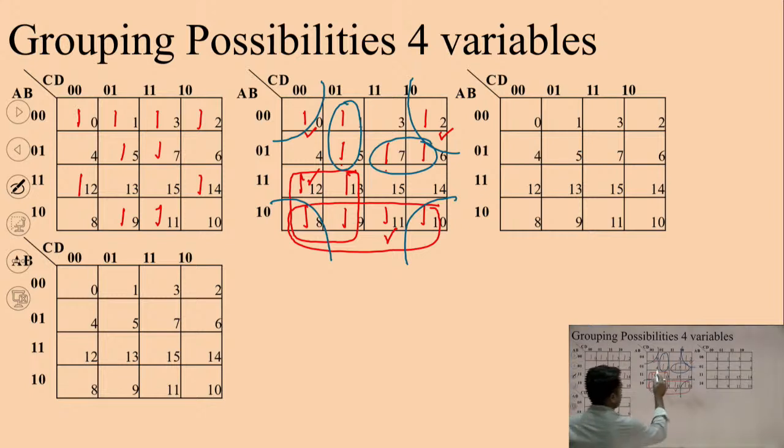And if we look at this carefully, there is a mistake in this. What is the mistake? The mistake is that this 1, 1 which I have made a pair can be easily extended into a quad. So you have to check for these possibilities, that this will not be a pair but it can be converted into a quad.